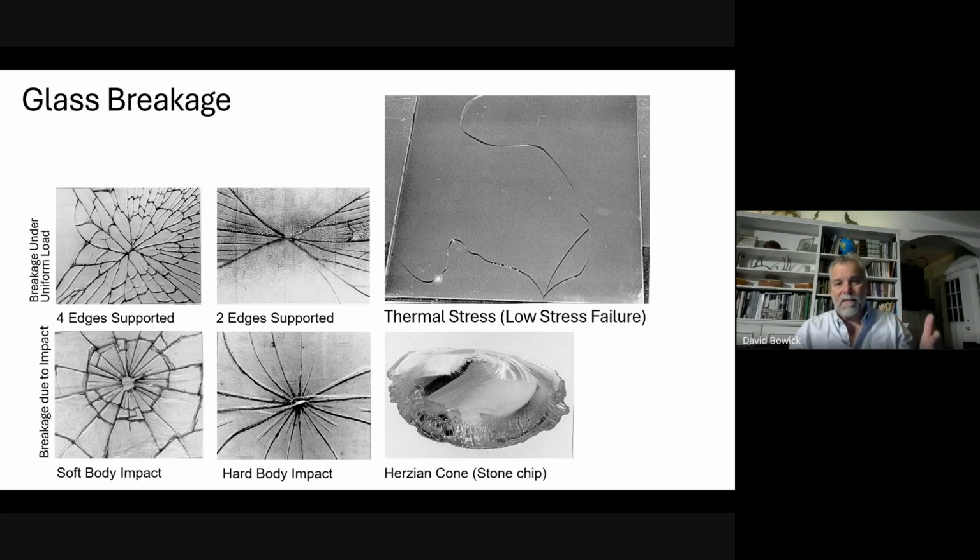Another example, again, a south-facing window, winter time. In this case, there had been snow and then a cold, sunny day, and the bottom portion of the window, there wasn't snow in contact, but the snow shaded the window. So there's enough heat lost through the window, even an insulated layer, that it melted the snow a little bit. The snow wasn't actually in contact with the window, but it did provide shade, and we wind up with a thermal crack starting at the bottom and working its way up.